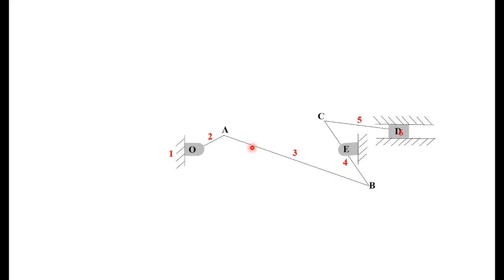Then we have the velocity of point A. We have to find the velocity of point B. Then what do you have to check? You have to check A and B belong to which link. So this is common to which link? Link 3. So which center do you have to locate for that? I13 only. So you have to locate I13. We already located it in the previous diagram, so I will show it again.